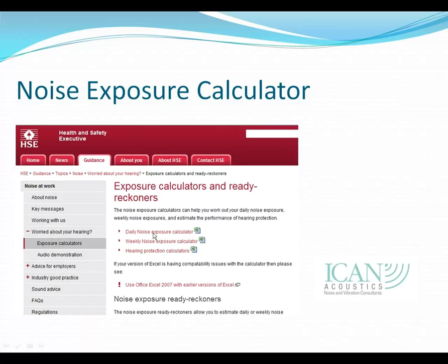So using measurements, once you've measured the noise source accurately using the proper instrumentation, you can work out, based on the number of hours spent, for example, on a specific machine, what their likely daily exposure level is, or indeed their weekly exposure level is.